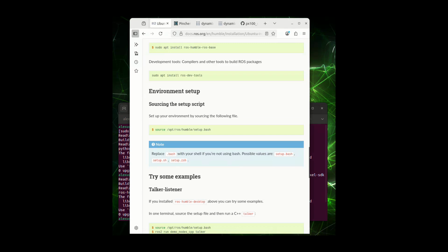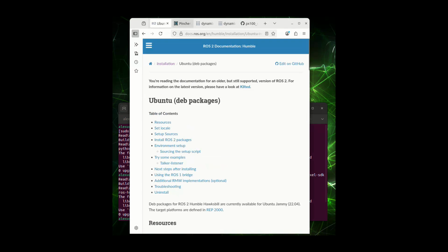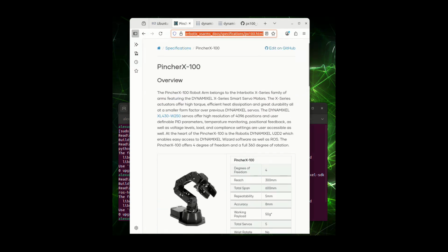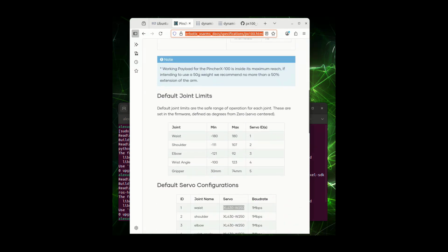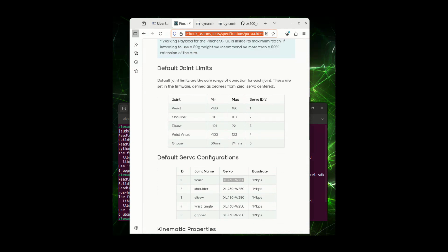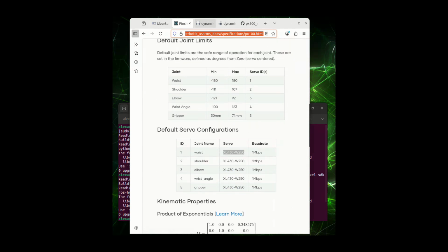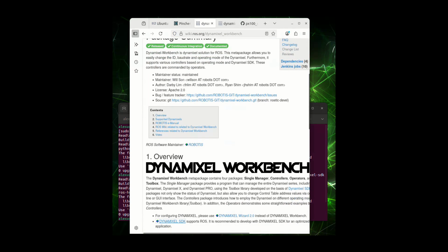But the difference between using that Python SDK from Interbotix and using the more direct Dynamixel SDK, which is one of the ROS2 packages, is that the Dynamixel way is ROS2 compatible. The Interbotix GitHub and those packages are for ROS1. That's why they work for me on my ROS1-enabled Jetson Orin Nano, but my Jetson Orin AGX is ROS2 enabled.